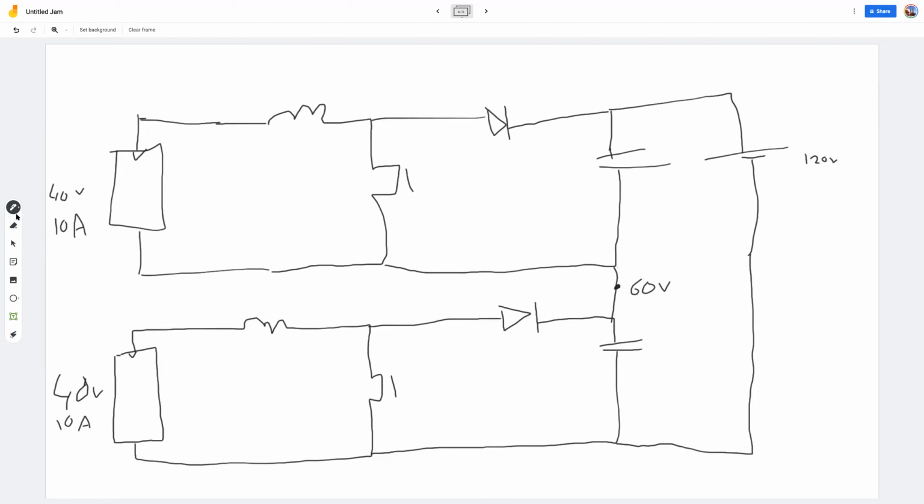But now let's say you get a little bit of shade. Or no, let's first look at the curvature. Let's say it's curved, and this top MPPT gets 10% less. Because it is curved a little bit and not pointed at the sun as well, it gets 10% less energy. So the current would be 10% less, which is 9 amps. Now this intermediate voltage here in the output changes as well, because they both have different powers and they both have the same current.